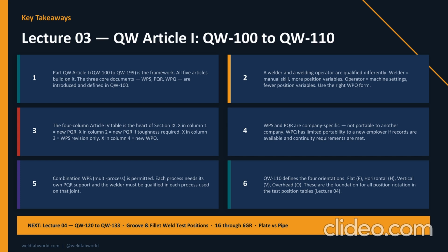4. WPS and PQR are company specific. A PQR cannot be taken to a new company and used without that company qualifying their own procedure. WPQ records have limited portability with conditions attached: records available, continuity maintained, new employer formally accepts.